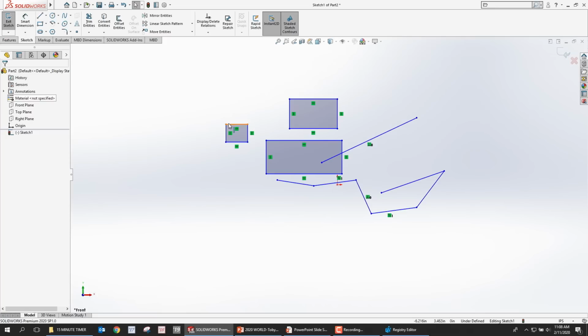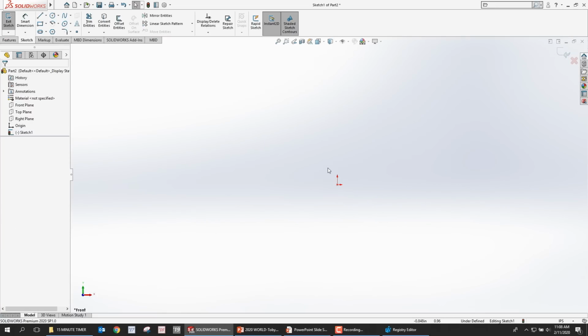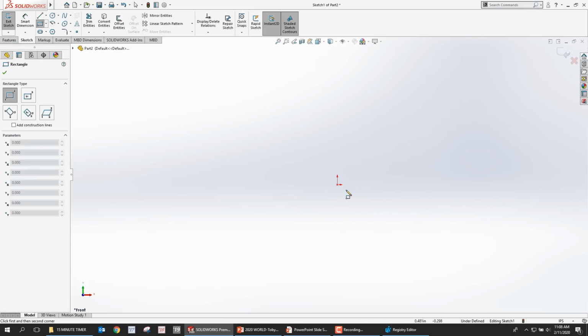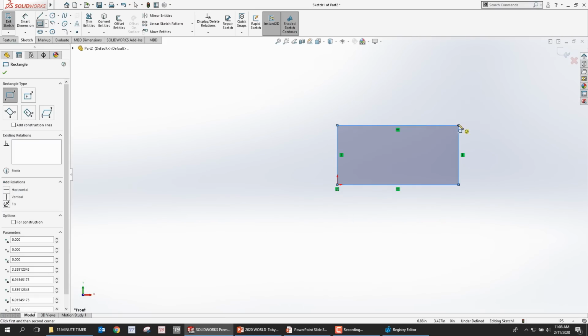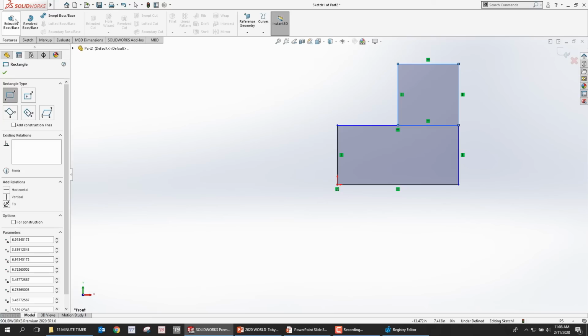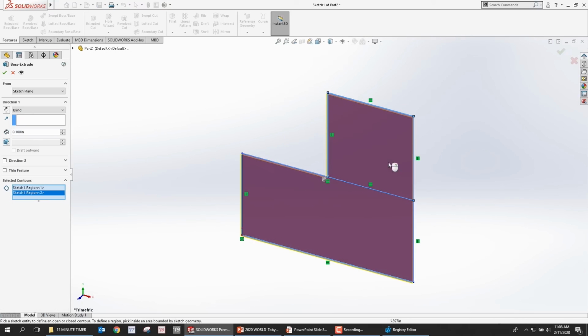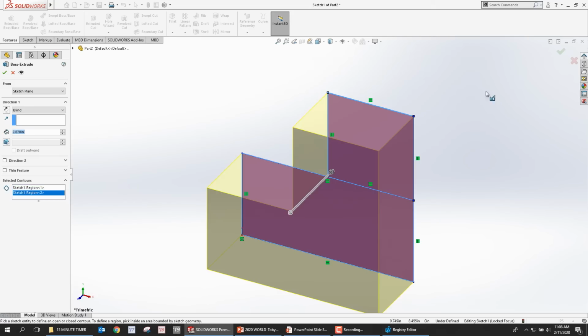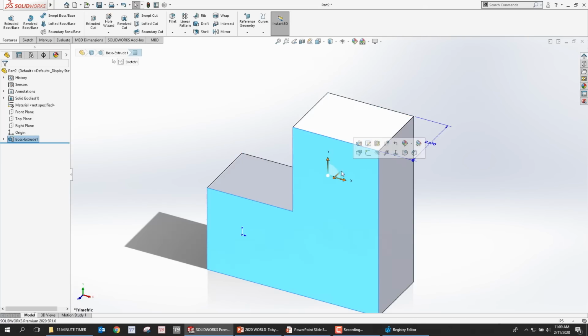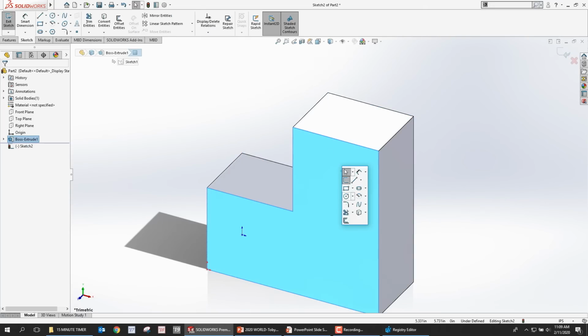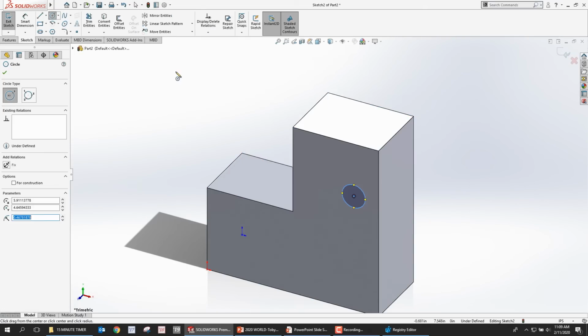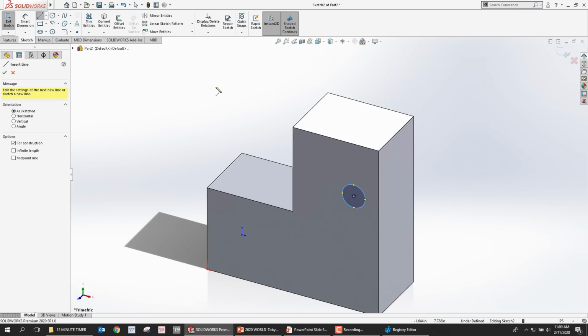And although it's maybe a little bit of a fringe case, the spot where I use that knowledge to my advantage a lot is when I'm in a situation where I want to quickly center something like a hole. So let's say, for example, I go into a boss extrude command here, and I want to create a hole that is centered along this face here, horizontally. So I'm going to create a circle here, I'm going to add some dimensions, and then I'm going to come in with a center line command.